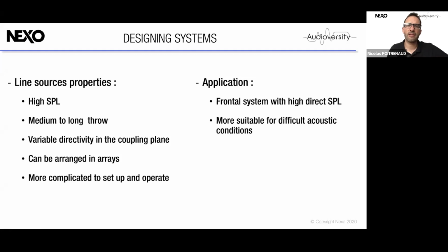So what I recommend is always to look at the coherency between a main system and a delay system. If you run, for example, your left and right, it's very much the same as when you measure delay on the field. You never measure the delays with both left and right running at the same time. The main reason is that there are so many arrival times coming from the different systems that it's impossible to visualize the impulse response on your screen.